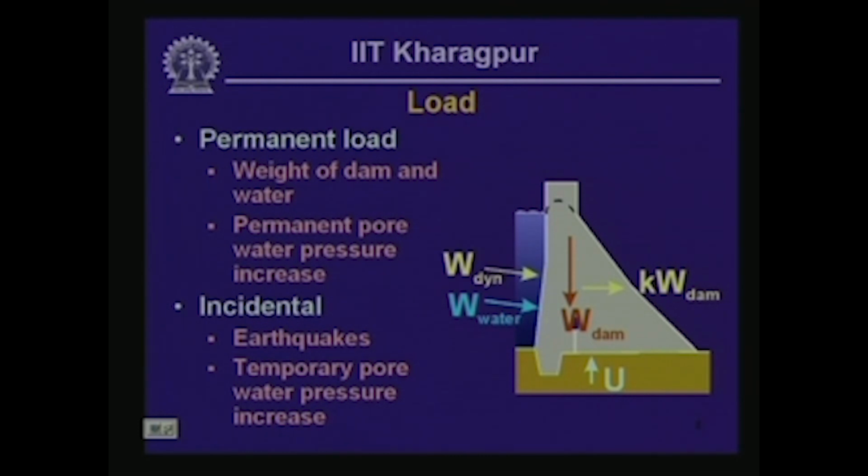Then in addition to it, we could have a dynamic water pressure because of earthquakes or because of water waves caused by strong winds within the reservoir. So these are the incidental loads, a few of them anyway, that need to be transferred to the foundation.